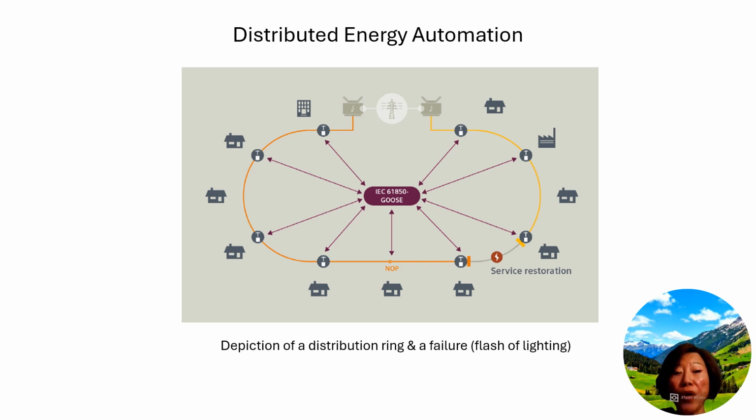While the service bit rate per controller is low during steady-state operations, GOOSE message bursts with a high service bit rate occur, especially during fault situations. Multiple or all controller units of the feeder send GOOSE messages nearly simultaneously during the fault location, isolation, and service restoration procedure, ensuring low end-to-end latency.